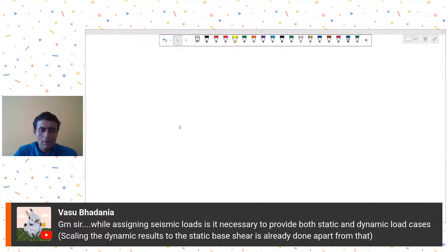Now let me have a quick look at the queries that have been put in the live chat. Mr. Vasu Badania is asking, while assigning seismic loads, is it necessary to provide both static and dynamic load cases, and is scaling the dynamic results through a static base shear already done?